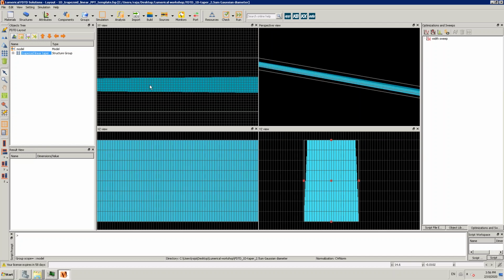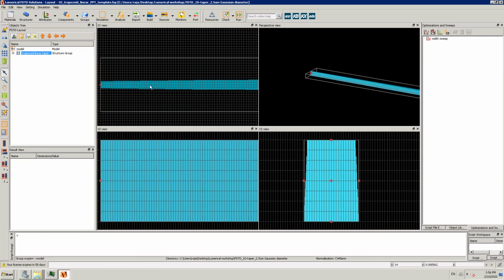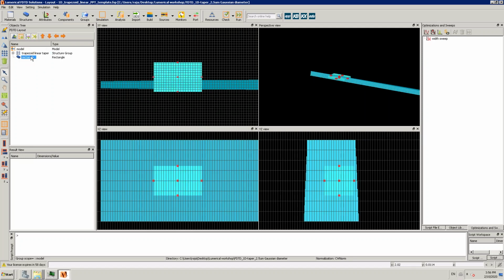What do you do next? So now I'll try to add the oxide. If you go to structure, because for the oxide we don't care, because you have a nitride, it has sidewall angle, but for the cladding, you can just put a rectangular waveguide. So I will put a rectangle here, okay, and now I need to adjust different parameters for this one.